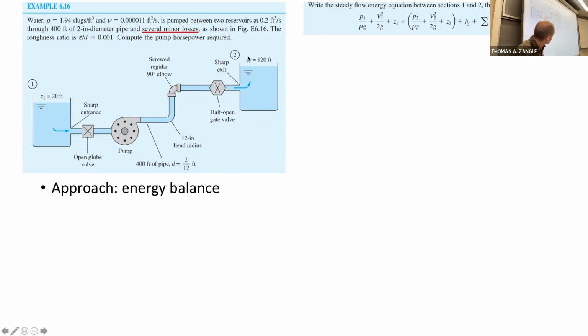And you'll see on those exam problems, for some of them, I am asking you to eventually find how the liquid level in the big reservoir is changing. But on one of those problems, I tell you, you can make a quasi-steady assumption where you assume that basically this level is not changing, so this velocity is approximately 0.